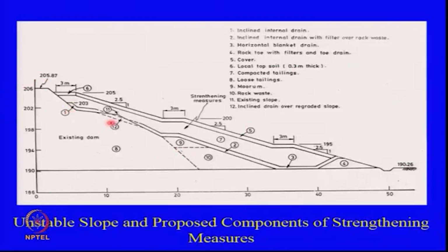Okay, you put a sand drain here, but the tailings will still come out from here, because there's an interface between the tailings and the rock. How do you prevent this tailings material from coming out by putting a drain at the top? It doesn't work. So you have to re-engineer this thing so that you can prevent the tailings from coming out, and then you can put the stabilizing berm.